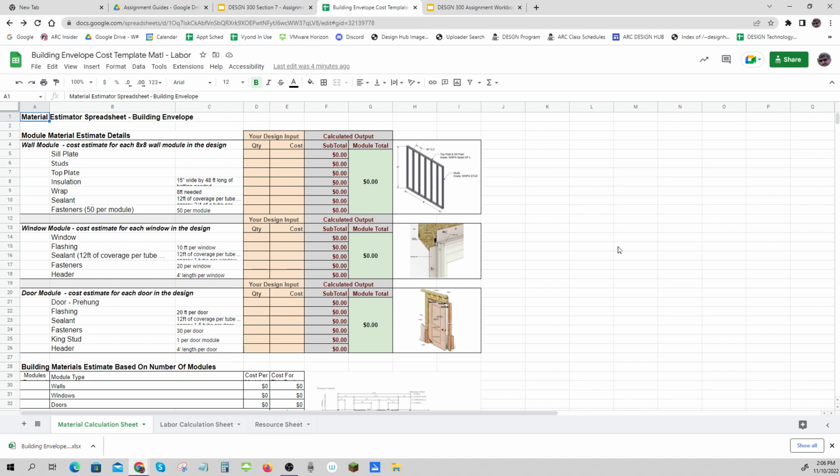So when we look at how a wall is made, and we're going to do some wood work, and we're going to put some stuff into that wood, we know that there are framed walls, and often designers work in modules of 8 feet long by 8 feet tall. That's a very typical size, and that's because many things fit that size very well. Sheetrock, OSB, plywood, even bricks all fit this 8-foot length very, very well.